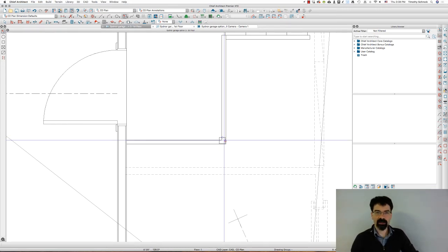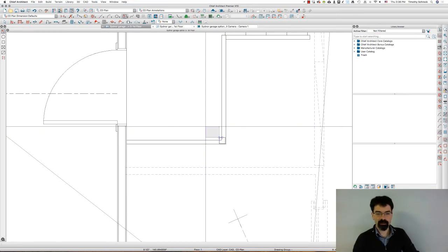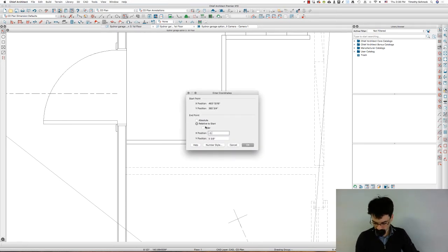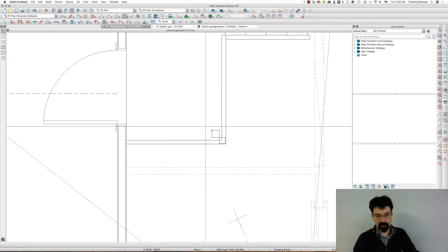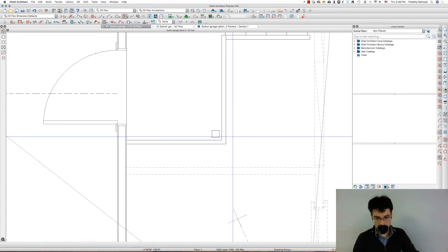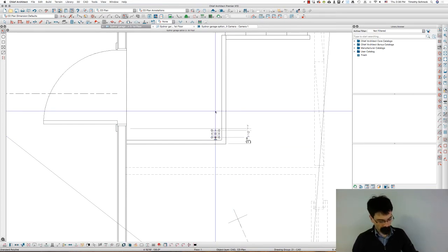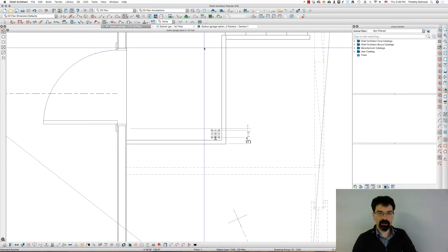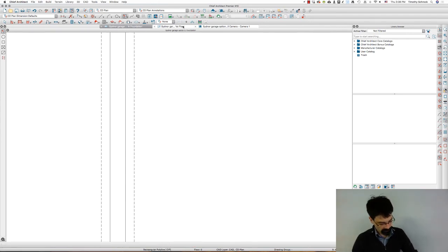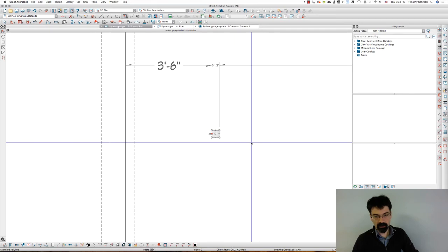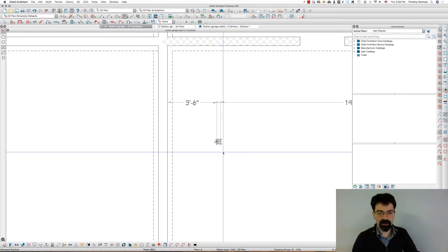That's going to represent the 2 layers of my 2x rim joist, and then from here I'm going to go -3.5, 3.5 for my post. I'm going to Command X, use Control X if you're on a PC, to cut, and Command Option V or Control Alt V on your PC. And that's exactly where my post should be.